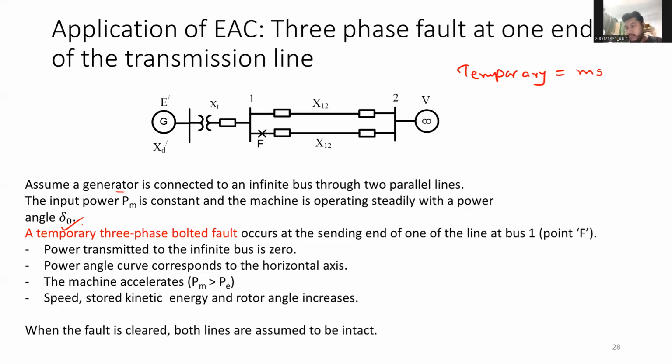Those require physical activity, and they are not a huge part of our analysis, because if your transmission line is broken, there is nothing that you can do just from your controller side. Someone has to go over there, amend those lines, then the system will come back on. So we are not considering that. We will consider the temporary fault. So that is the first thing.